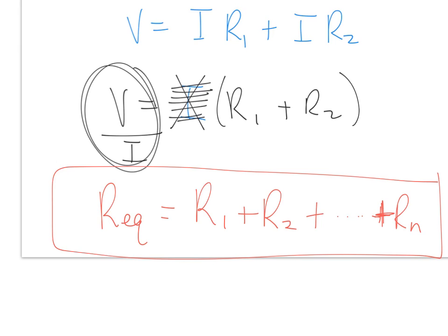Here's what this is saying. If for some reason, in part of my circuit, I had two resistors that were in series, and one resistor was 5 ohms, and the other was 3 ohms, and they were in series, I could simply add the 5 and 3 together and replace them with an 8 ohm resistor. An equivalent resistor, which is the sum of the other resistors' resistances. Again, an equivalent resistance comes from the sum of these other resistors that are in series.